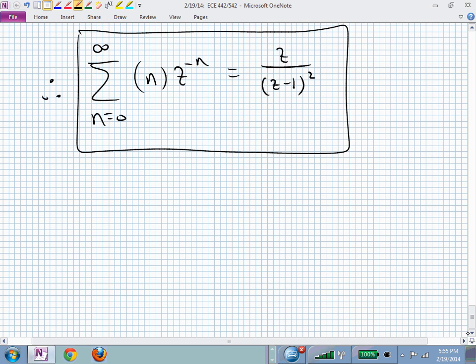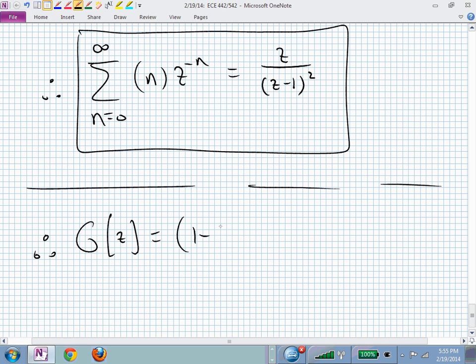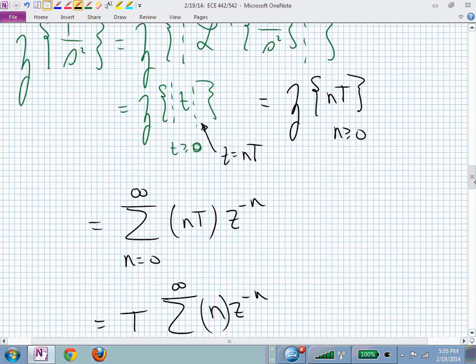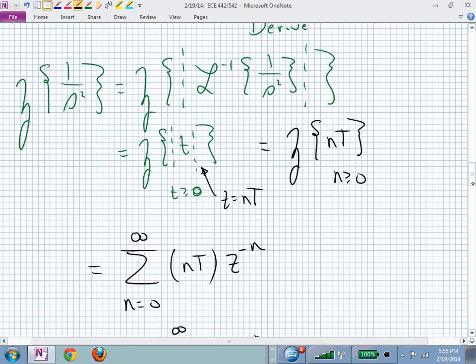which now allows me to find this z transform of 1 minus z to the minus 1 of k over s squared, which is what I was hoping to find somewhere. Wow. There. I need this 1 over s squared, and I found that I needed this for its z transform. And I didn't know what that was equal to, and now I do.